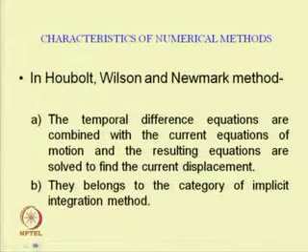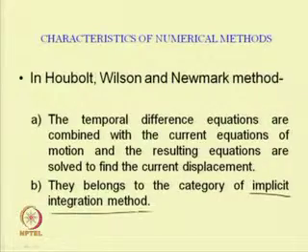So, we will now see the Houbolt, Wilson and Newmark methods. In these methods the temporal difference equations are combined with the current equation of motion and the resulting equations are solved to find the current displacement. They belong to the category of implicit integration methods.